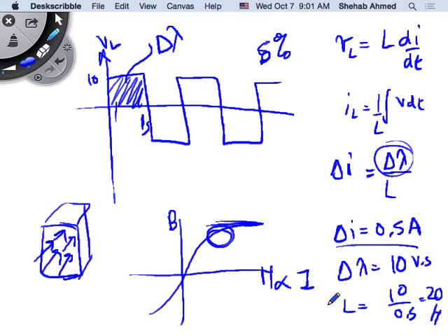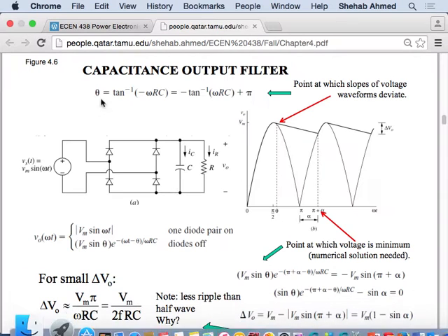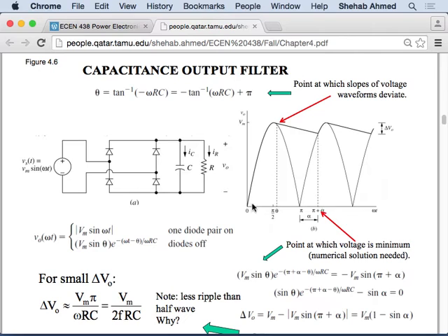So high frequency power converters, if I want to deliver 1 kilowatt using these simple rectifier circuits that we're talking about, the AC-DC converters that we're talking about, are very simple rectifier circuits. These are operating at what? 50 or 60 hertz, right? The waveforms that we see here are what? Up to here, this is assuming 50 hertz input. This waveform is now at 100 hertz, right? It's double the input frequency. So this thing is operating at 100 hertz. So I need a certain capacitor, right?